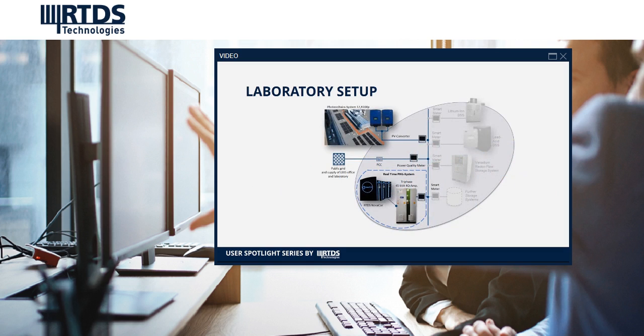Therefore, I disconnect all storage systems from the microgrid bus and I isolate the microgrid from the public grid as well, because the grid will be formed by the real-time simulation now. At the moment of isolation from the public grid, the PV system will recognize that by island detection and shut down to fulfill the standard, not to unwillingly maintain an islanded grid.